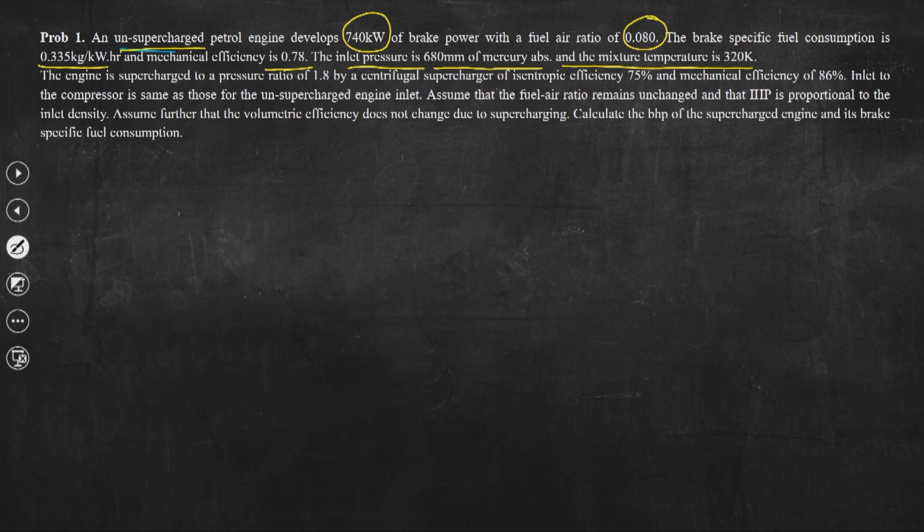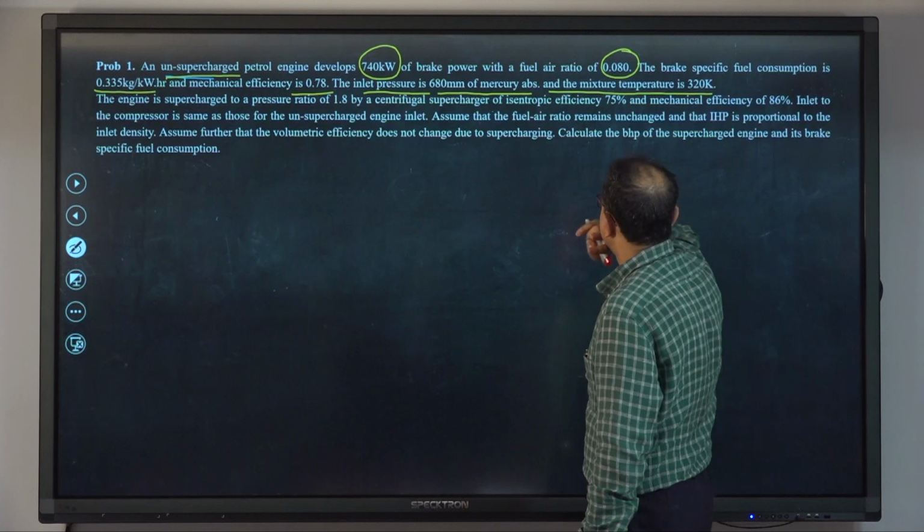So, typically for an SI engine during the intake stroke, charge is drawn into the engine cylinder, that is air fuel mixture. As I told you, even for the modern CI engines, it is not only pure air that is drawn into the engine cylinder during the intake stroke, rather there is a provision of supplying fuel in the intake manifold as well, because nowadays a multi-port fuel injection system is there, and hence it is not the pure air that is consumed during the intake stroke, rather it is air fuel mixture or charge. So, the charge condition is given, pressure and temperature.